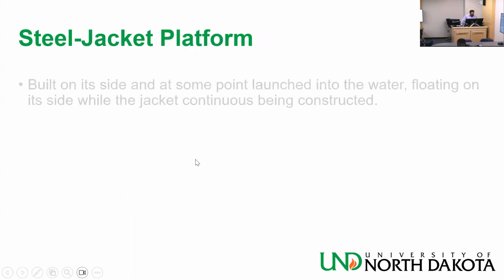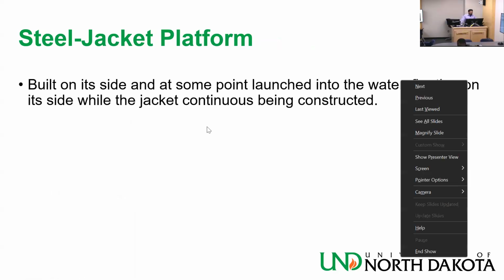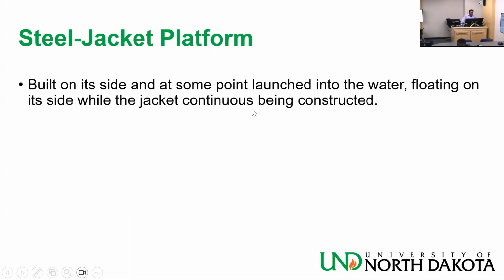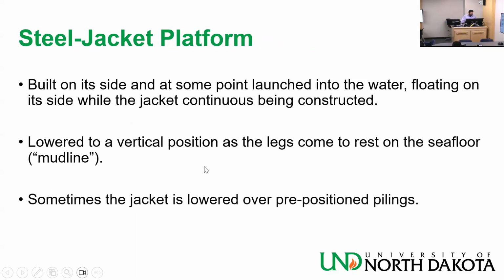The steel jacket platform is built on its side and at some point launched into the water, floating on its side while the jacket continues being constructed. I will show you pictures. It is lowered to a vertical position as the legs come to rest on the sea floor, the mudline.